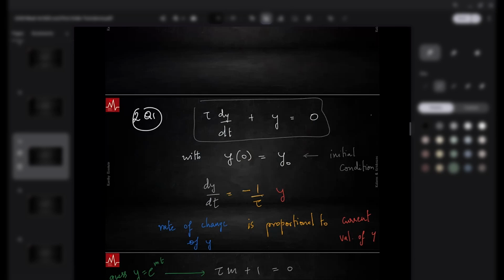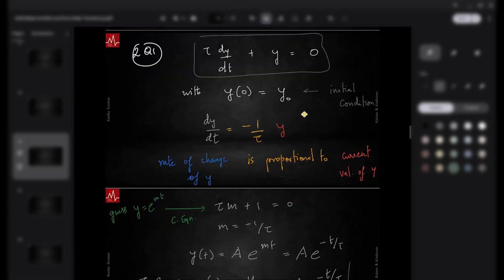So any typical first order system, RC circuit, LR circuit, the Maxwell model, Kelvin model, anything, MRI, bioinstrumentation, PCT, all of that, at least the starting point is this equation. Tau will change. Tau will be RC for an RC circuit, L by R for an LR circuit. Each problem will have its time constant, but this is always going to be this equation.